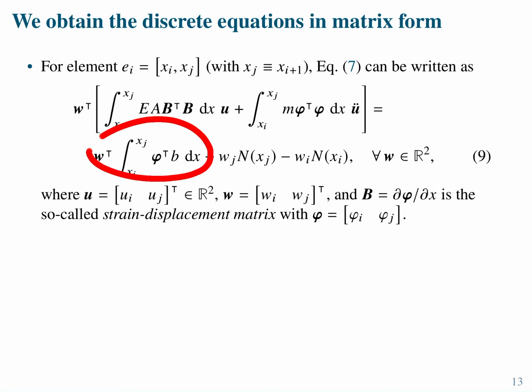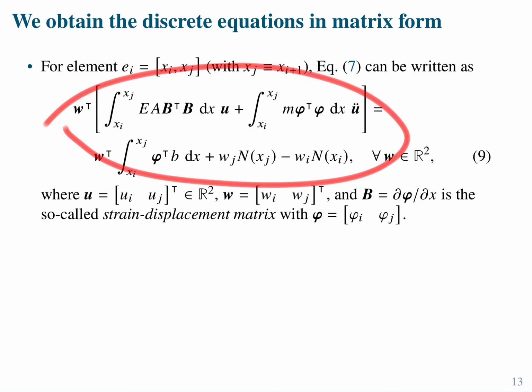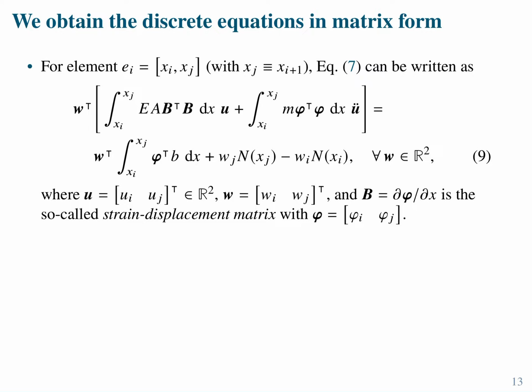So I have here the body force term, and I have essentially the axial forces at the ends of the element, not the boundary conditions of our problem, where we were looking only at the ends of the bar, the reaction and the applied axial force at the other end. No, here I'm looking at the axial force at the elements only, right? And so this whole expression, if I say for all W's in certain function space, that translates into all vectors W in R2 for that element.